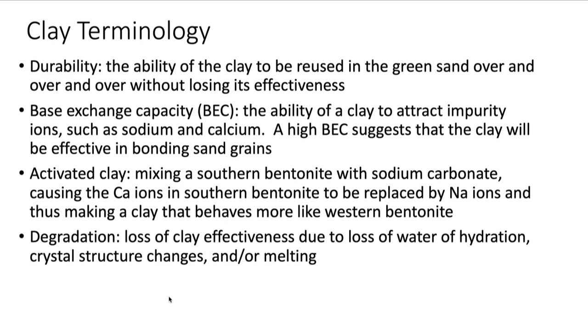They can't hold water. So the ability for the clay to attract the sodium and calcium is this thing called base exchange capacity. A high base exchange capacity means that the clay will be effective at bonding first of all the sodium and calcium, and then also bonding the water to the surface.